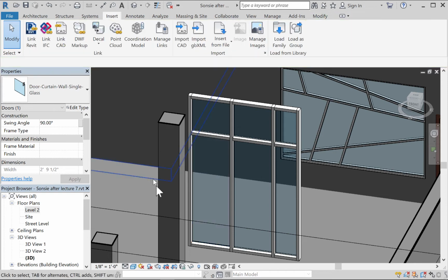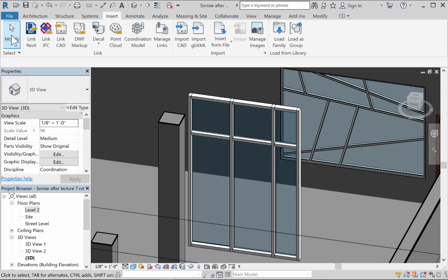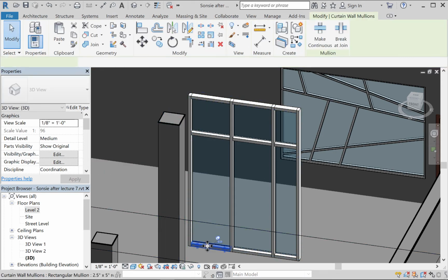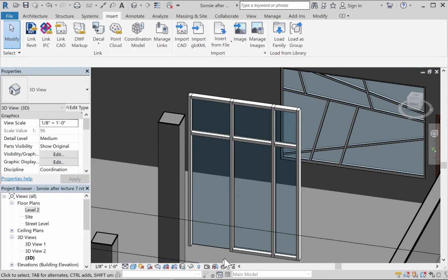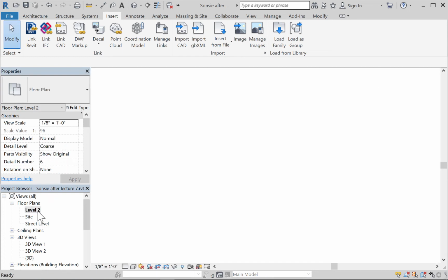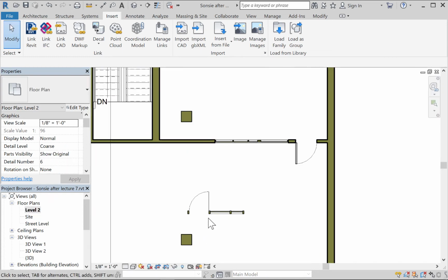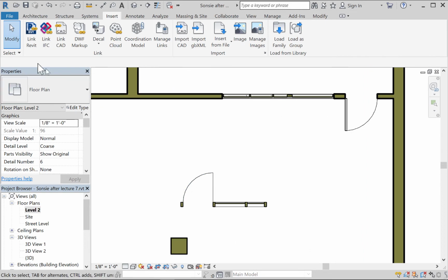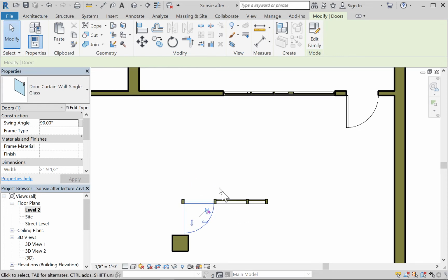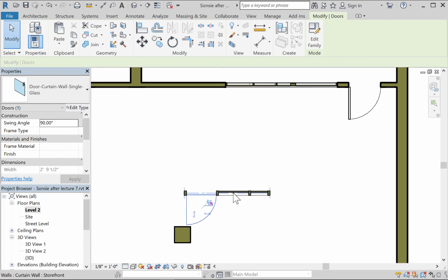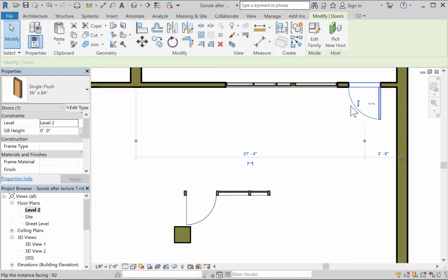And what you'll see is, well, it doesn't look any different, frankly, because a glass curtain wall looks about the same. I have to unlock this bottom bit so that now it's a door. If we go to Plan View, it should look like a door. Okay, see, there we go. It's a door. And like other doors, we can change its handing in or out, flip it in or out. Again, you can only do that in Plan. I'll just have this come in.